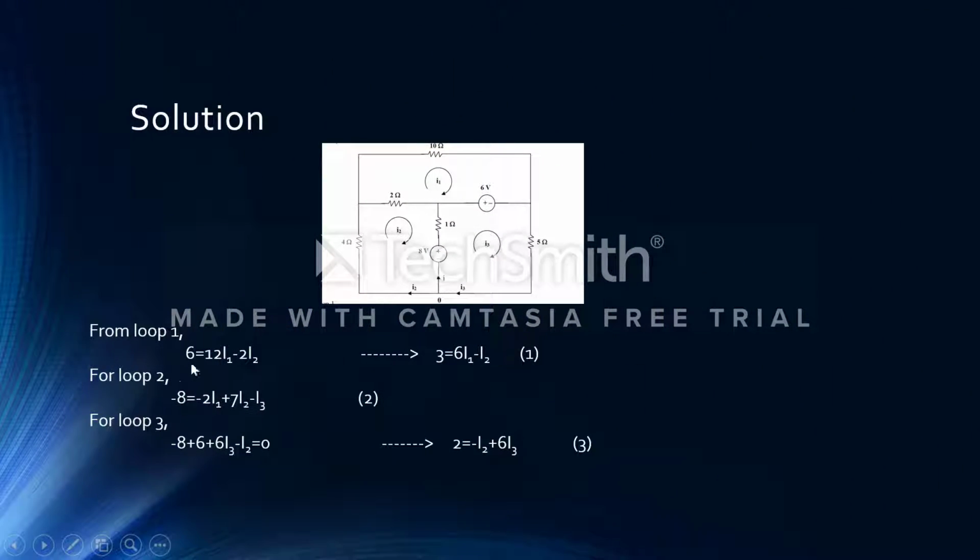And now for loop 2, minus 8 is equal to 2 times I1. So I1 flows through here, 2 times I1 plus 7 times I2. I2 flows over this 4, 5, 6 and 7, so 7 times I2. And I3 flows just through this 1 ohm resistor. So I3 is negative because it is moving in a direction opposite to I1. So for loop 2 we get minus 8 is equal to minus 2 times I1 plus 7 I2 minus I3.